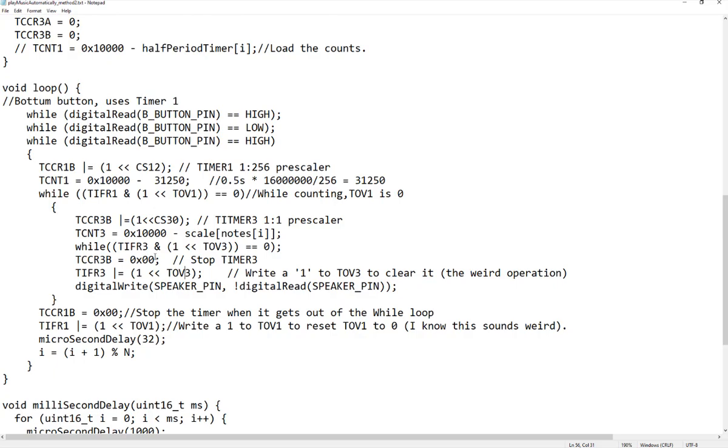So what I said probably was a little bit wrong just now. Actually when it's waiting there, it's just still during that half period. It's not flipping yet. It's not really playing the note. It's just holding at that voltage level. You know what I mean? It gets out from this while loop and then flips it. Toggle it over here to play the note. Any questions? Anything?